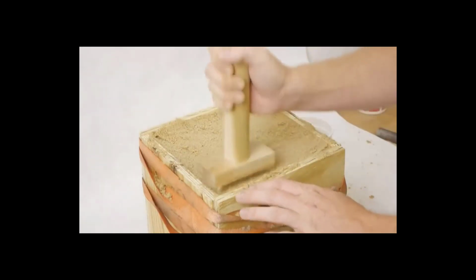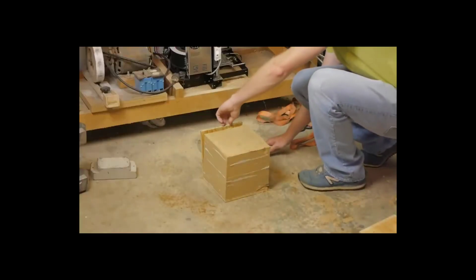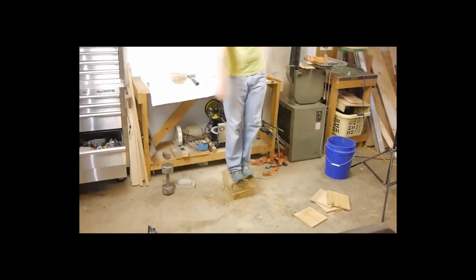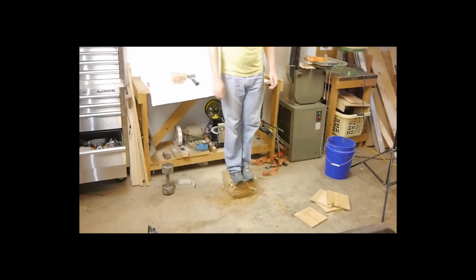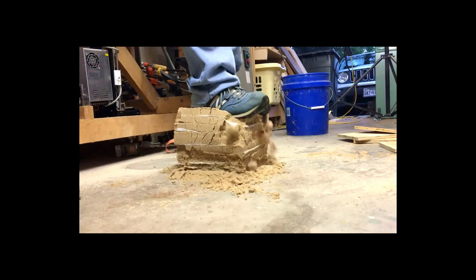This part is not to demonstrate the strength of MSE, but rather to show that the soil really is transferring load into the reinforcement. The t-shirt material is stretchy, so when the vertical load is transferred into the reinforcement, it spreads out and deforms. I wanted to demonstrate this because it may not be obvious in the next example.